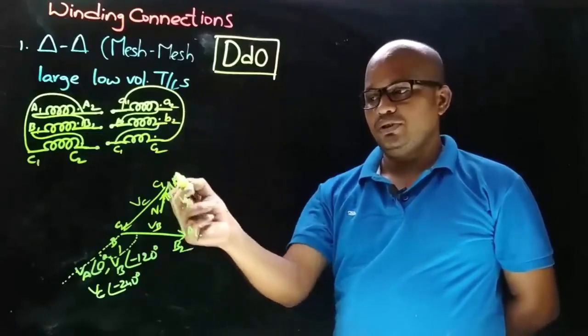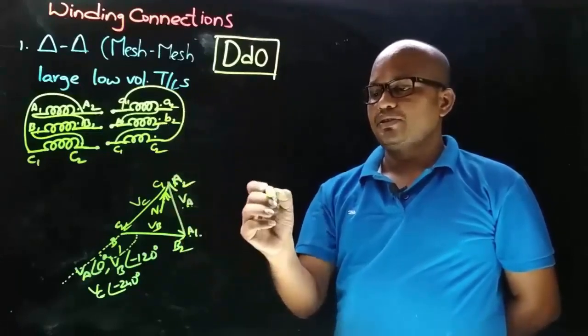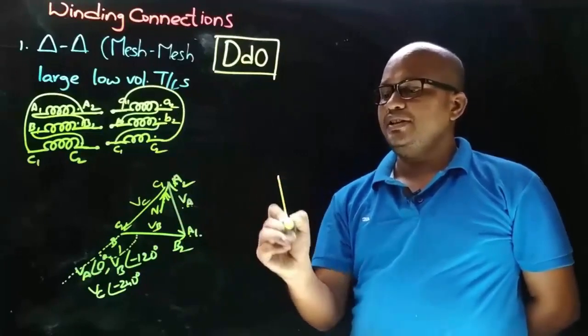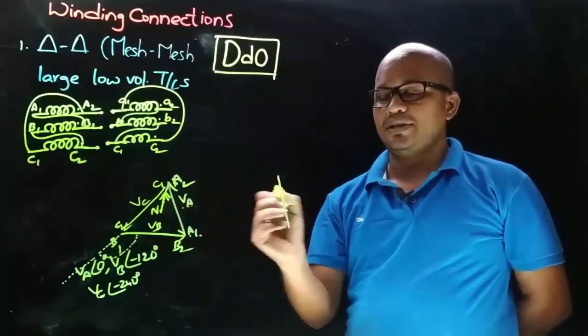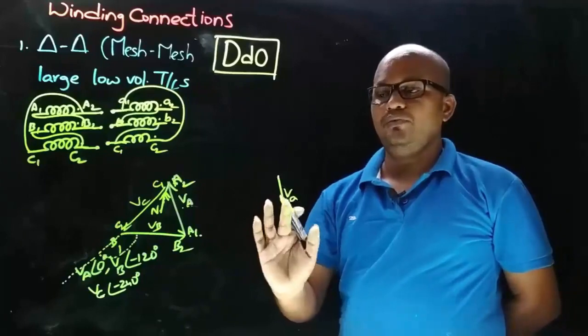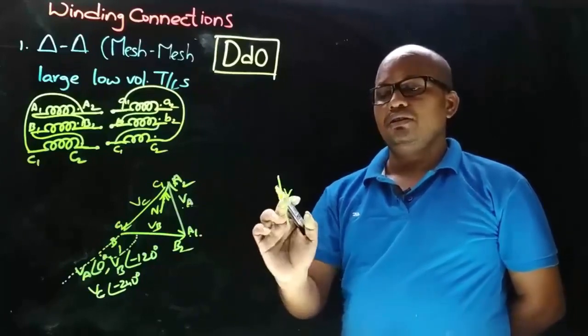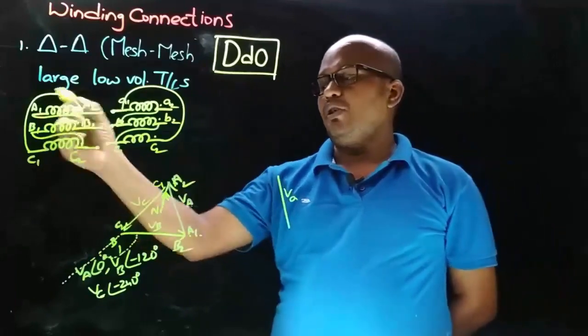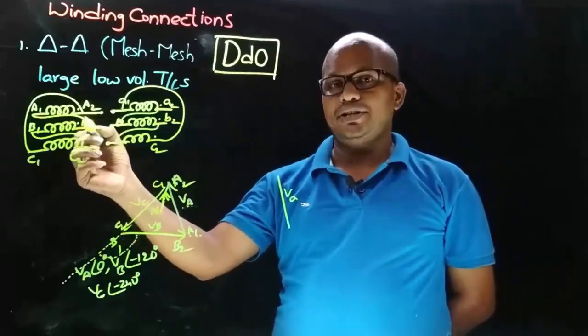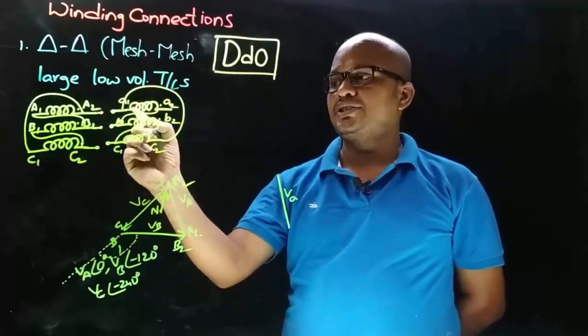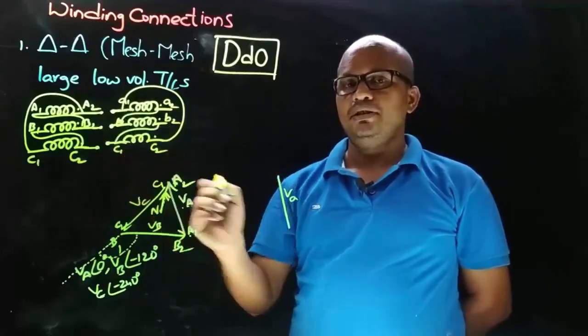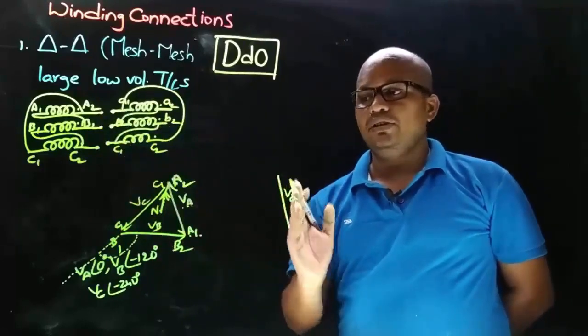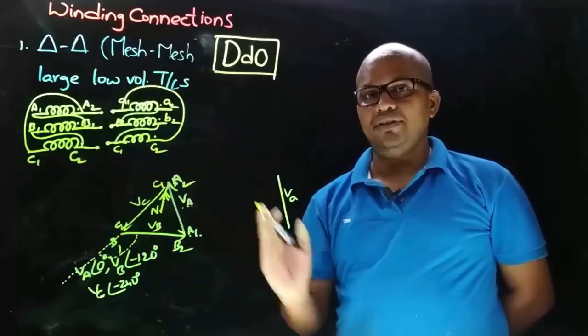So first we took primary side VA, so the secondary side VA will be parallel to primary side, and now we need to decide the direction. So direction of phasor depends on the connections we took from. On this side connections are taken from dot ends, and now on secondary side connections are taken from non-dot ends, means the secondary phasor will be in opposite direction to primary phasor.